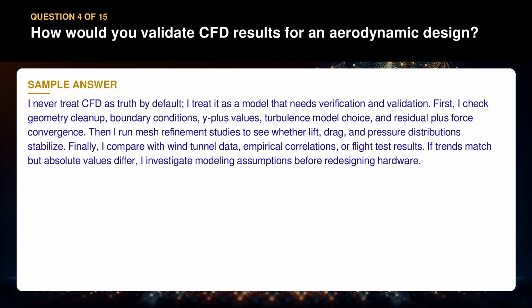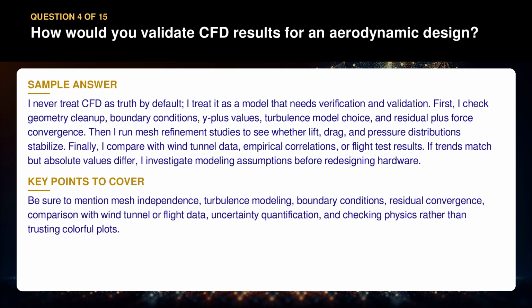If trends match but absolute values differ, I investigate modeling assumptions before redesigning hardware. Be sure to mention mesh independence, turbulence modeling, boundary conditions, residual convergence, comparison with wind tunnel or flight data, uncertainty quantification, and checking physics rather than trusting colorful plots.